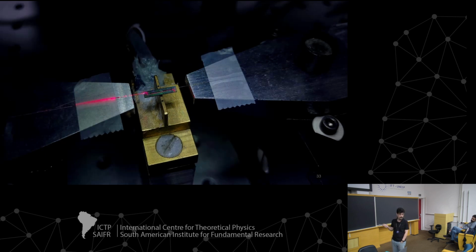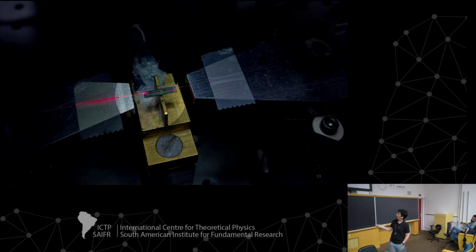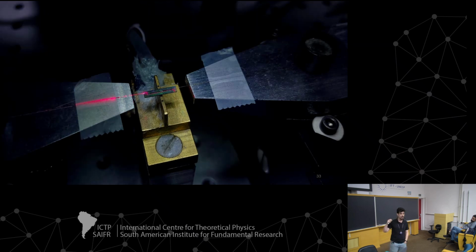Okay, so just one input, one output for the first tests. Later, you want to come with fiber arrays and couple these fiber arrays to your chip, and maybe do it permanently. So this is what's called packaging the chip. The electrical connections here have not been made yet. You have the electrical contact pads on the chip, but we still need to wire bond everything in order to drive the heaters and implement whatever we want to implement.